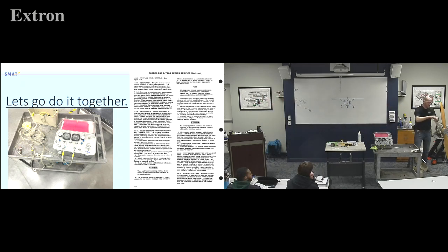But if you have the good tools, we're going to get fancier and fancier as we go. This is one way to plug into your static port on your aircraft. Notice there's still a hole on the side, right? So he's stuck good. I would highly recommend, before you use these tools, to make sure that the hoses aren't leaking themselves before you do all this. I did that already today on a set, but you might be changing hose ends. So the way to do that is you can just put a piece of the putty or whatnot on the end of your hose. Well, I might need a helper up here because it doesn't want to stick.